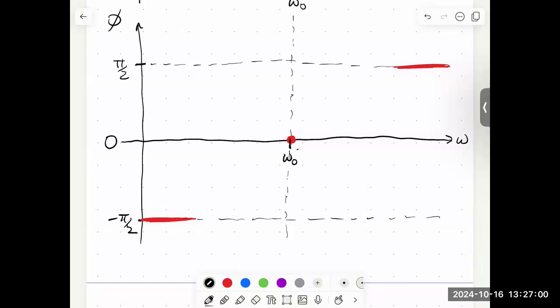You can show your function generator on channel 1 and your voltage across your resistor on channel 2. Then you adjust the frequency until their phases align so that they peak at the same time. And that will be one way, a very nice, quick way of finding your resonance.